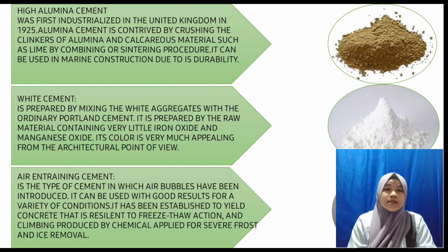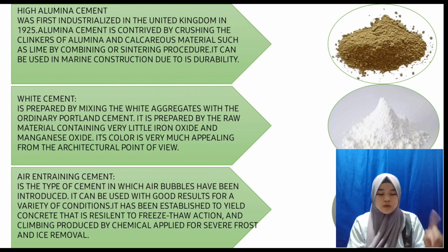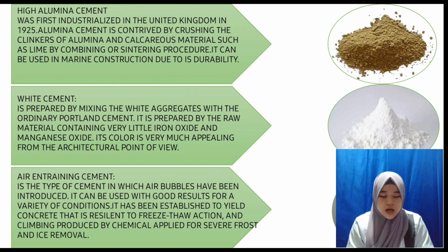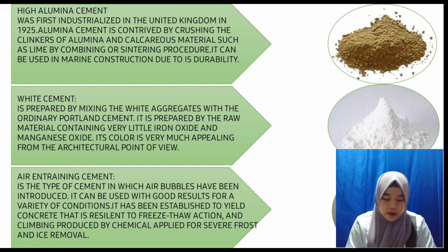So it is a special cement which has air bubbles introduced in the cement or concrete that provide the space for expansion. The workability of the cement is high due to the air bubbles, which act as lubricant between aggregates, which reduces water and sand requirement and hence increases the strength of the concrete. But it is difficult to attain high-strength concrete with air entrained cement.